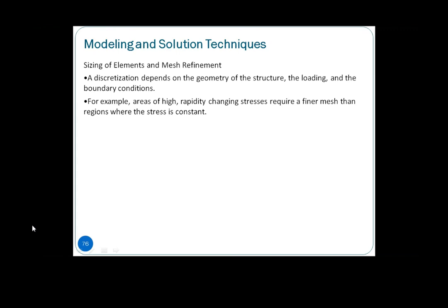But in the case where you are moving towards very localized problems like stress, especially stress concentration, where it only gathers at a certain localized point, then at that particular localized point you need a better mesh, a smaller or more refined mesh, or a larger number of elements in this case. So that is one of your considerations.